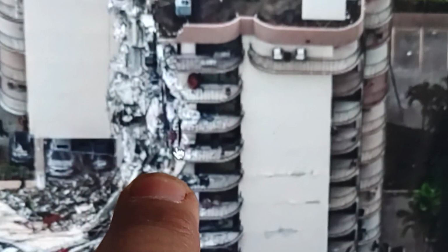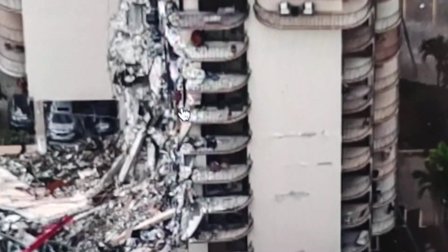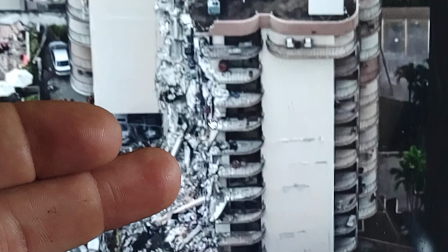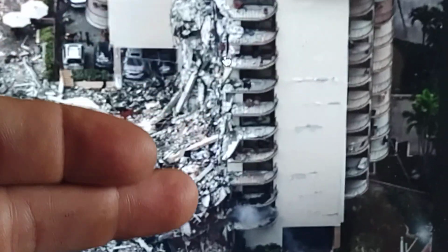And as we see that in the debris field above, that was part of my pointing out when I pointed to this piece of slab here, saying, "Oh, look at that pattern." I wasn't really talking about looking at the pattern. I want you to notice the levelness of the deck beyond it. I also wanted you to notice the hook rebar and the rebar direction, and that tells you where your rotation starts taking place and how consistent it is. And that's all inside here. All that's in there, but we'll get to that in another video.